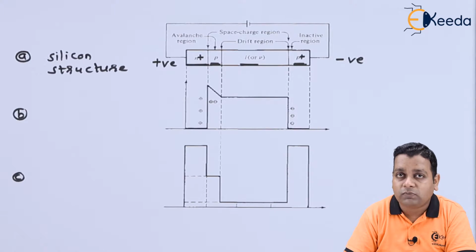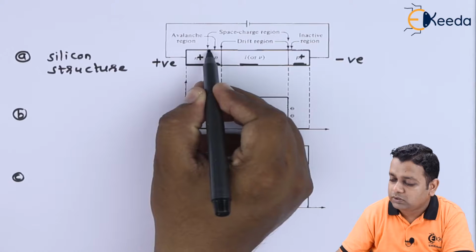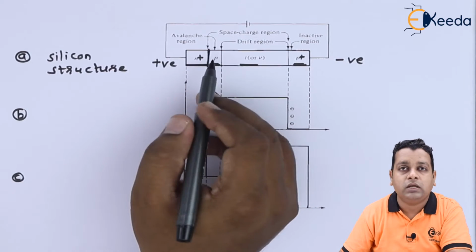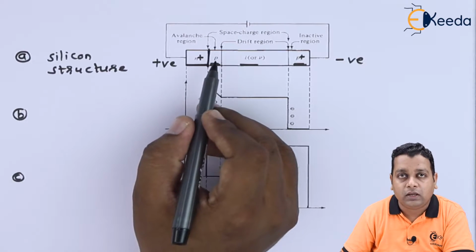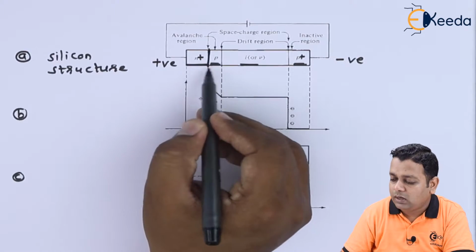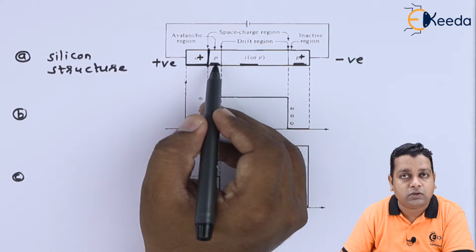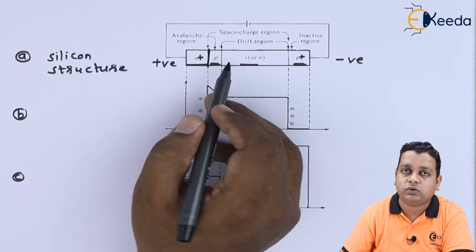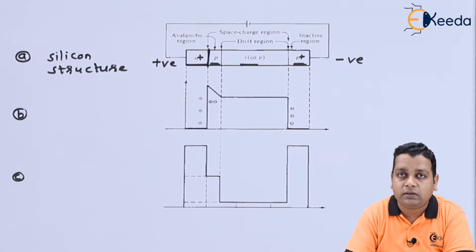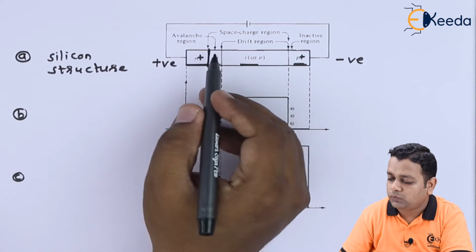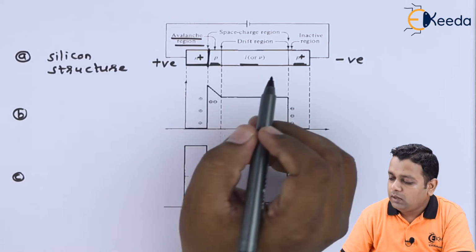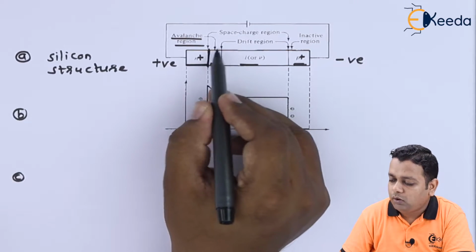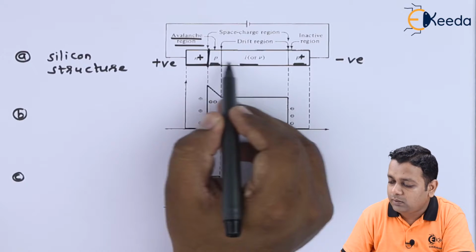So this is reverse bias operation with respect to the first junction between the N plus and the P. Therefore, the avalanche takes place in this P region, because of the heavy breakdown of charge carriers, so we name it the avalanche region. It then forms the high field domain that will drift through this.